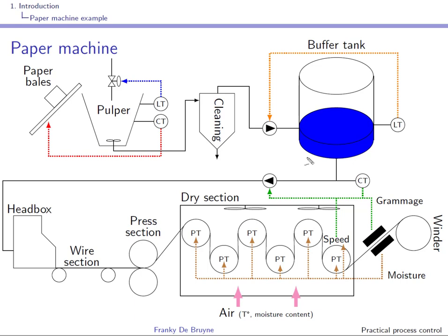In this drawing, it looks as if the internal model controller is directly interacting with the pump. In reality, here you have a flow transmitter, and you have also a local stock flow control loop. So what is happening is that you have an internal model control. This is the master. It sets the stock flow set point, and this local loop is implementing this stock flow control.